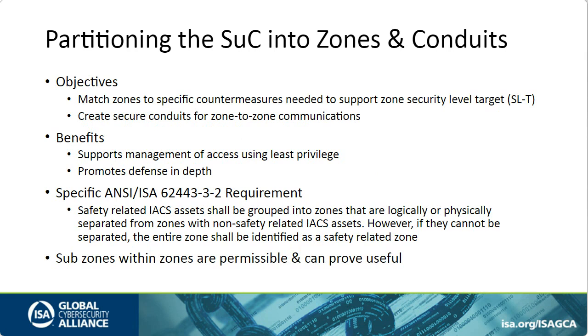So when you partition it, just to reiterate a couple things we've already said, we want to match the zones to the specific countermeasures needed to support the zone security level targets. And we want to create secure conduits for zone-to-zone communication. Some of the benefits: it supports management of access using least privilege, and it helps to promote defense in depth. It does not provide defense in depth all by itself, but it certainly enables defense in depth.